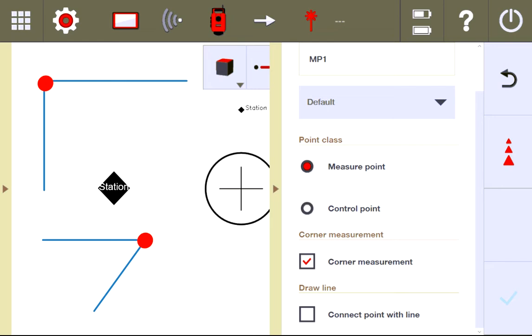The first measurement is going to be the point on one of the walls where the corner is. And you're going to want to get as close as possible to the corner, but not too close to where you're not sure if you are bumping the other wall or not. For me, I usually find that if I get within a half inch, I'm okay, and I'm confident that I'm actually on the specific wall before the corner. The second measurement is the corner itself. You center the laser as best you can right there on the corner, and you measure that corner as well.